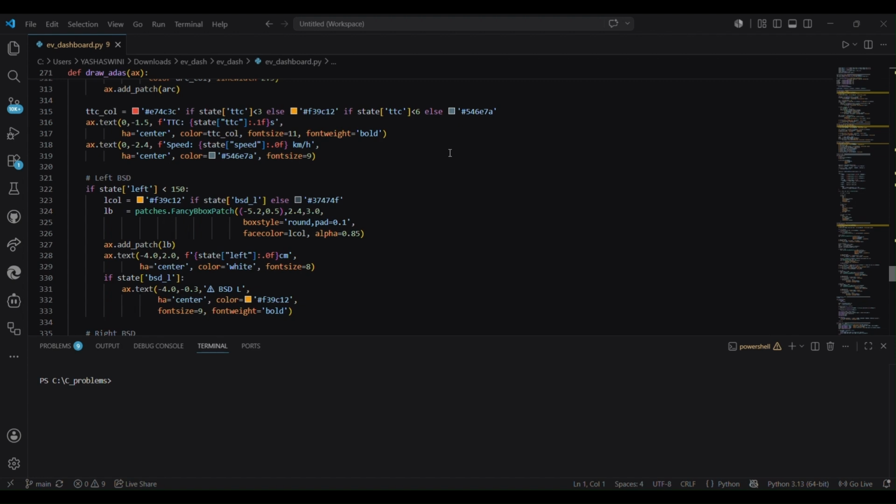Overall, the firmware follows a modular architecture. Main.c coordinates the execution while each module performs a dedicated function, such as vehicle control, obstacle detection, fault management, and UART communication. This modular design improves readability, debugging, and future scalability.